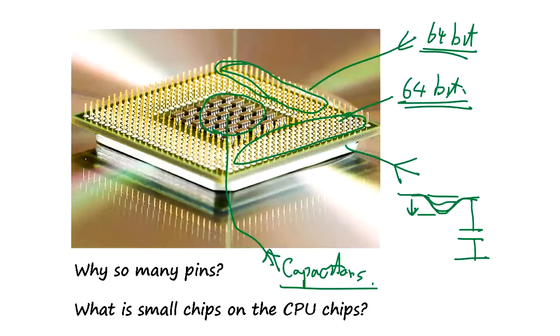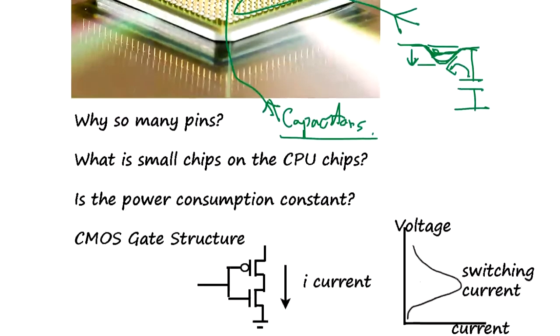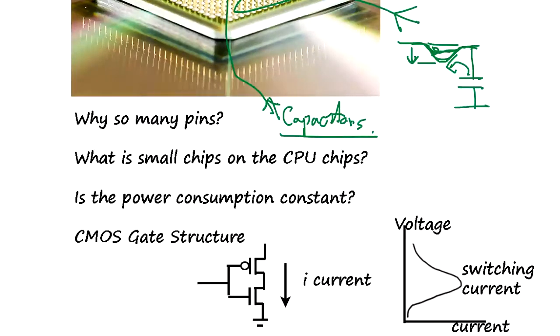So when it starts dipping, the capacitor provides enough current to bring it up. So those chips are usually capacitors, a lot of capacitors around the chip. And the power pin is not just one. Power pins are distributed, and the ground pins are also distributed to balance out all the power supply.